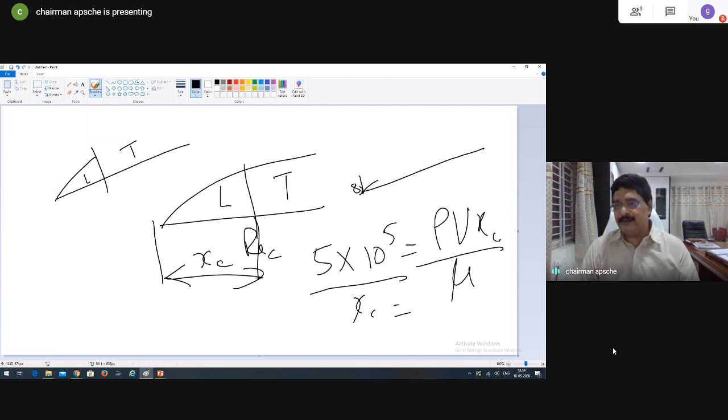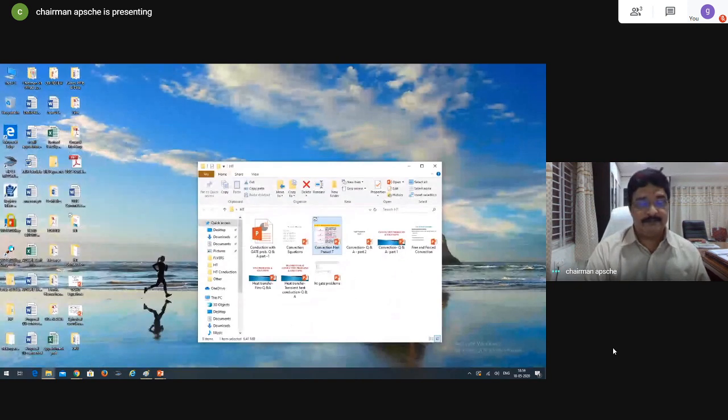Or the other possibility is that at the trailing edge, the value was greater than critical Reynolds number, therefore it is turbulent. And that means for some distance it is laminar and for the remaining distance it is turbulent. Or you can assume that because the plate is long, the laminar region is very small, you can ignore that. Assume that the entire plate is turbulent. So all these three possibilities are there for you in the calculation, right?